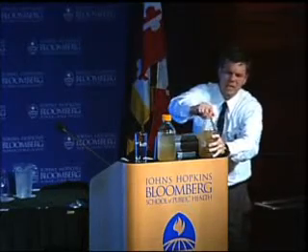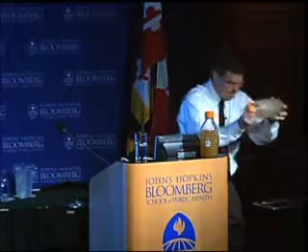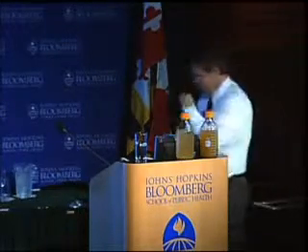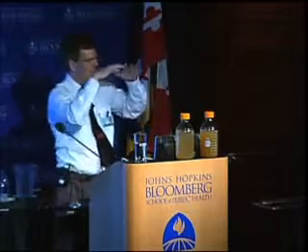So this is just a diagram of that. So what we do is we flash mix it. We rapidly mix this. And this alum is going to form in there. I'm a science nerd. So we got one in there. And then this gelatinous mass will form. You can watch that or me, and it'll slowly settle out.